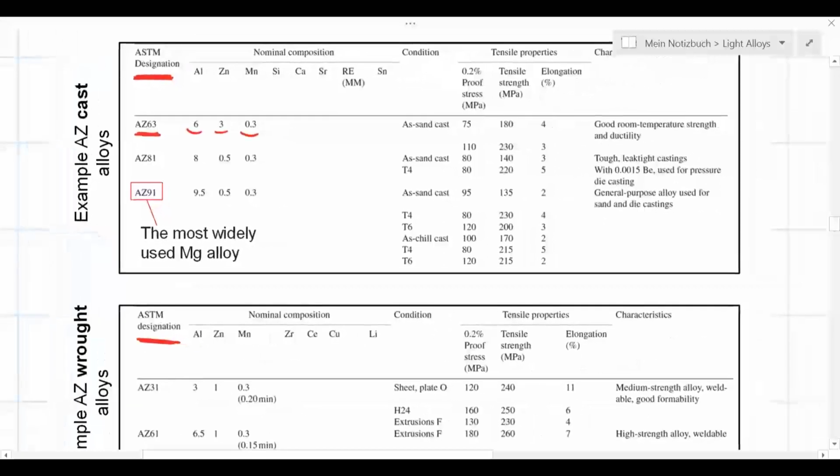Good. Then some tensile properties, if they are produced by casting, they are not as high quality as wrought products. So if they are produced by high pressure die casting, we know that they suffer from porosity. Liquid metal is entering the cavity at a very high velocity, and that could result in the formation of porosity. So gases could enter the melt, they get entrapped, and by that we get a lot of gas porosity. So that is one of the drawbacks of cast parts, especially if you are using high pressure die casting. This is one of the concerns.